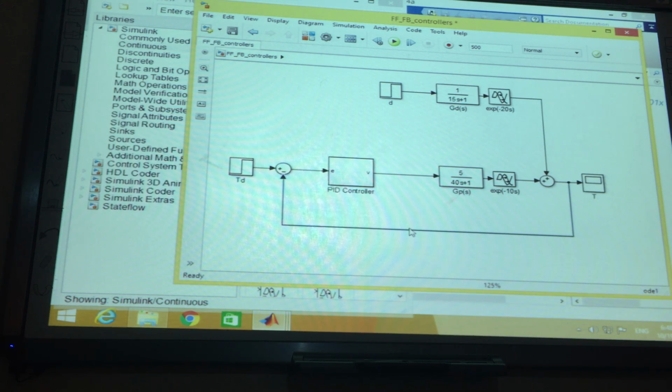So can we make it open loop? Can we make it open loop? What do you mean by that? Because no need to measure the error, because we have PID controller, so output equal input. No. Look, to reject disturbances, external disturbances, environmental disturbances, any other disturbances, you have to have feedback controller.